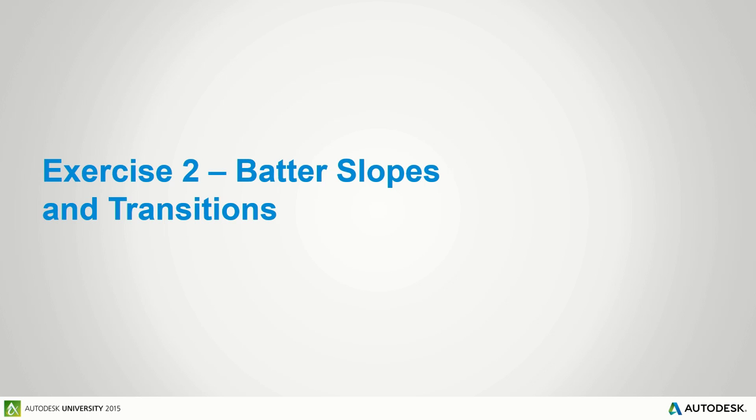So we're going to determine first, are we in cut or are we in fill? But not only that, we're going to add additional conditions to determine, are we in shallow fill or are we in deep fill? And we're going to adjust our daylighting of subgrade accordingly. So it sounds pretty complex, but it's actually not too bad.